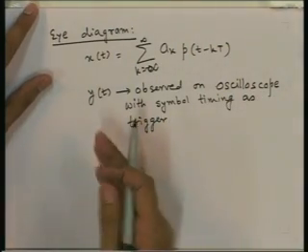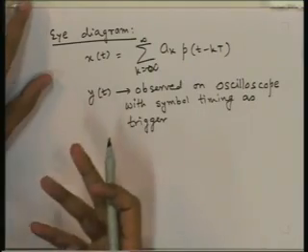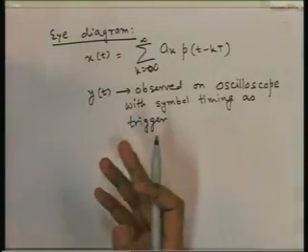We will take the signal, we will generate a trigger from that, which will synchronize with the symbol timing. Once we have a trigger synchronized with the symbol timing, we can give that on x and the y(t) in the y signal of the oscilloscope. Then we will see one or a few symbols on the oscilloscope.